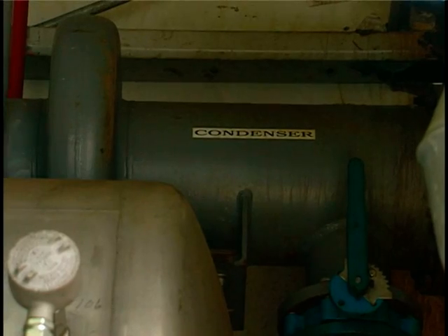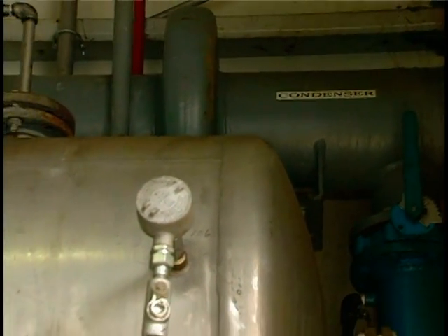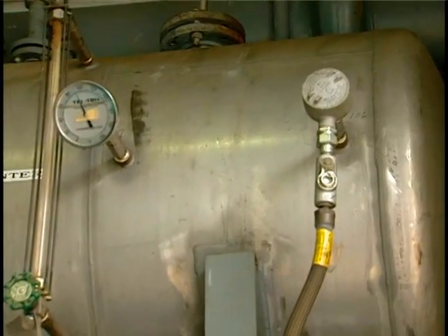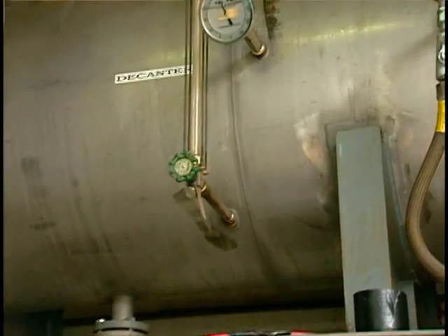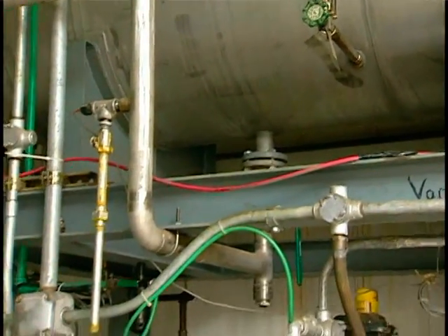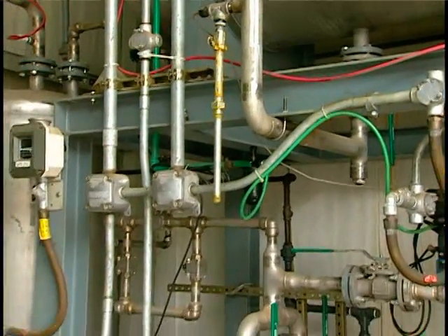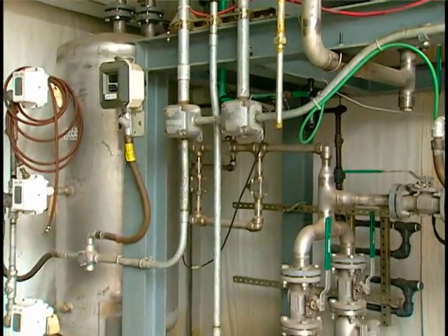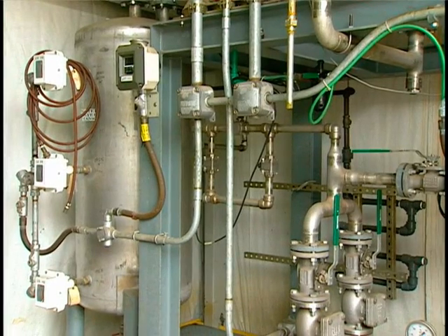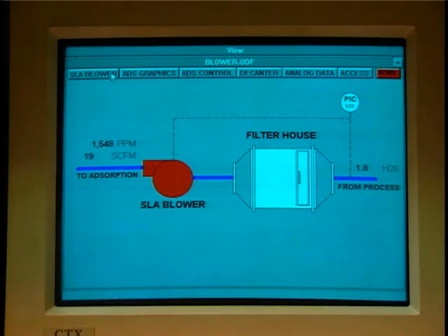Moisture in the gas stream can also affect retention. Water will adsorb onto activated carbon, competing with the organic contaminant for adsorption sites. Since adsorption is also affected by the presence of liquid and solid particles in the gas stream, particulate matter must be removed before entering the adsorber.